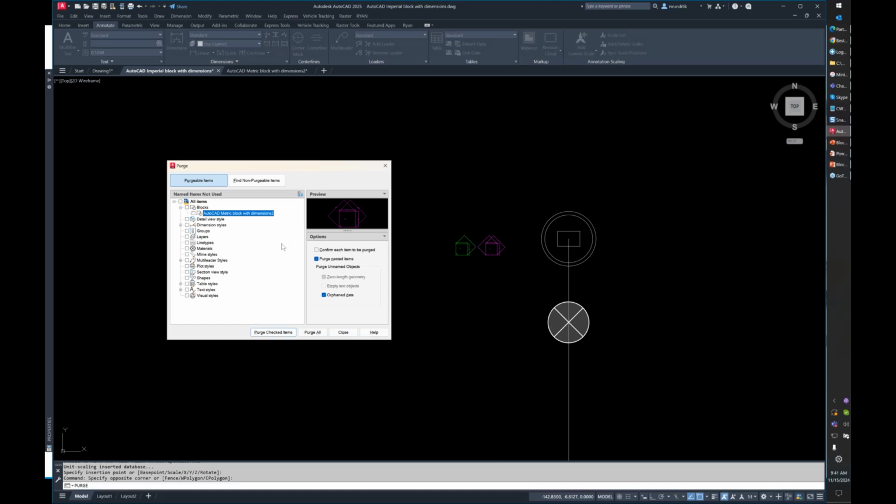Pitfalls with cloud drives. Oh, that is a very good one. So, James, that is a very good question. Broad brush, Autodesk does not support cloud technology except for BIM 360 and ACC. You can put block libraries up on BIM 360 or ACC. Honestly, for the most part, you can put them on Google Drive, Dropbox, SharePoint, things like that. There are some pitfalls with some of those, like SharePoint and OneDrive don't have good file locking. So if you are trying to modify a block drawing, somebody can come in and open that drawing from underneath you, and they can save over your changes. Those are usually the pitfalls.